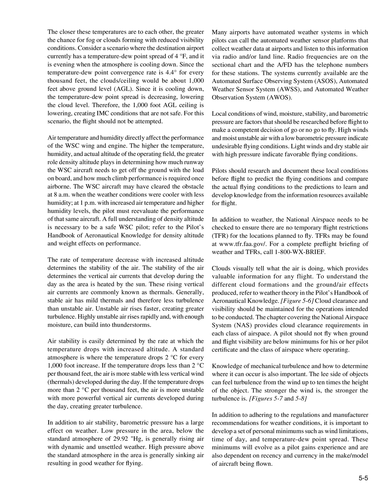Air temperature and humidity directly affect the performance of the WSC wing and engine. The higher the temperature, humidity, and actual altitude of the operating area, the greater role density altitude plays in determining how much runway the WSC aircraft needs to get off the ground with the load on board, and how much climb performance is required once airborne. The WSC aircraft may have cleared the obstacle at 8 a.m. when the weather conditions were cooler with less humidity. At 1 p.m. with increased air temperature and higher humidity levels, the pilot must re-evaluate the performance of that same aircraft. A full understanding of density altitude is necessary to be a safe WSC pilot.